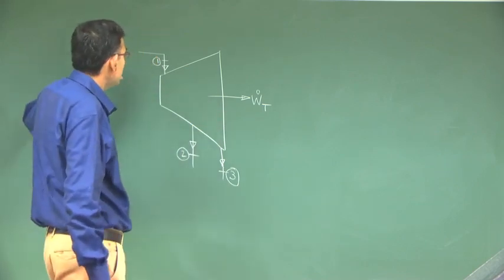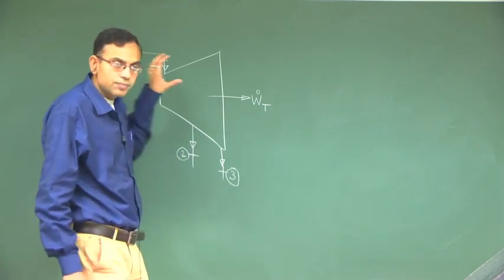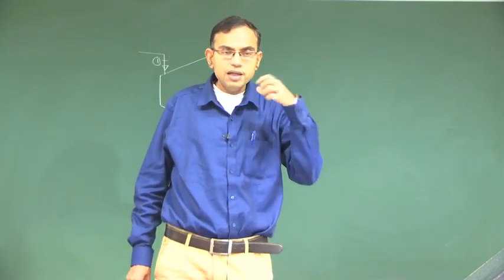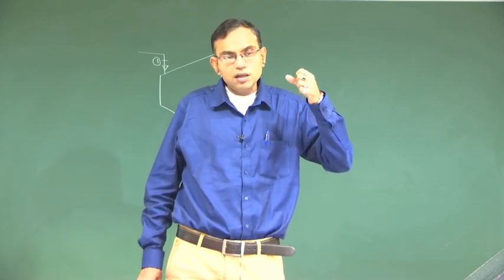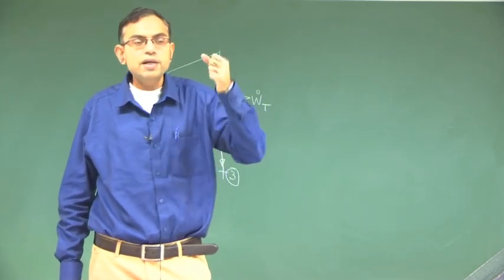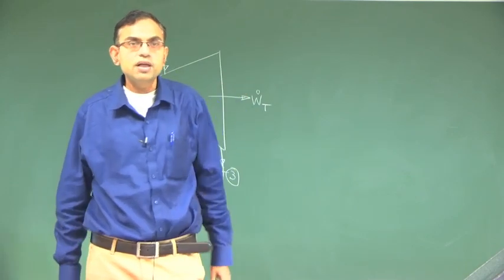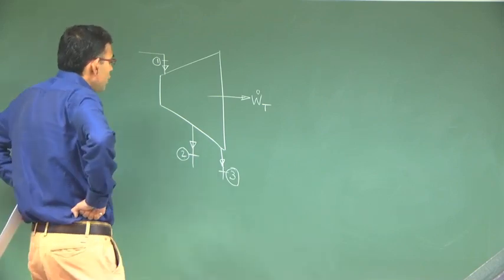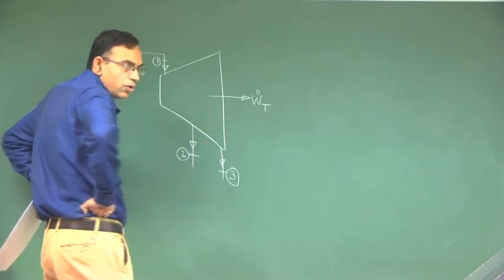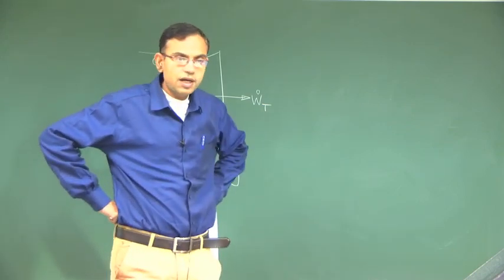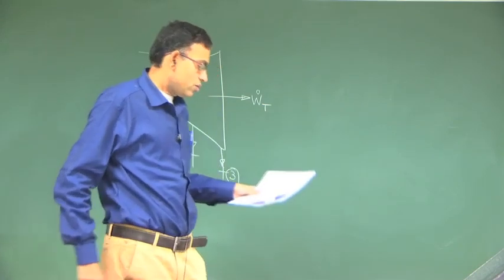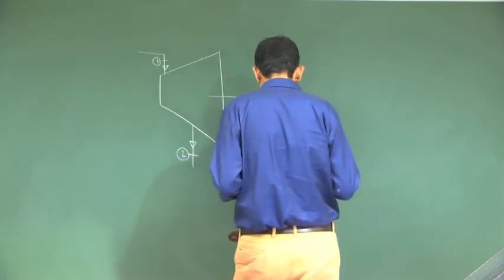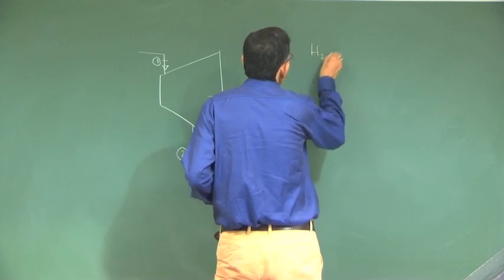First, steam with high thermal energy enters the nozzle, which converts the thermal energy to kinetic energy, and then with a very high kinetic energy the steam falls on the blades of the turbine and the blades start rotating like this. So, the turbine is a work producing device, that is for sure. In this case, let us note down the properties. The fluid is water,